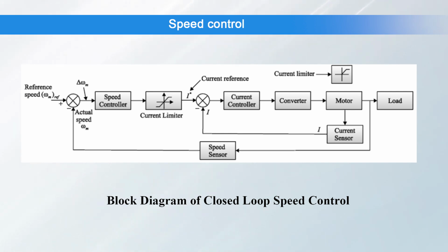As the speed rises, the speed error reduces and the current and torque therefore reduce to obtain a smooth approach to the target speed. We will now look in more detail at the inner, that is current control loop, as its correct operation is vital to ensure that the thyristors are protected against excessive overcurrents.